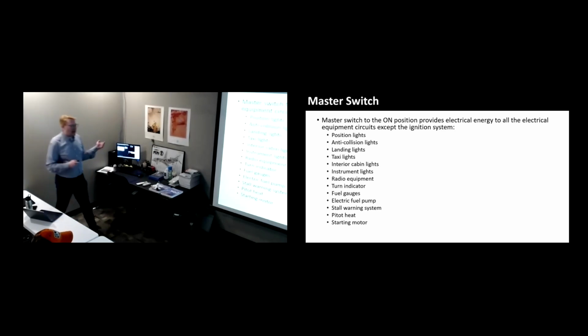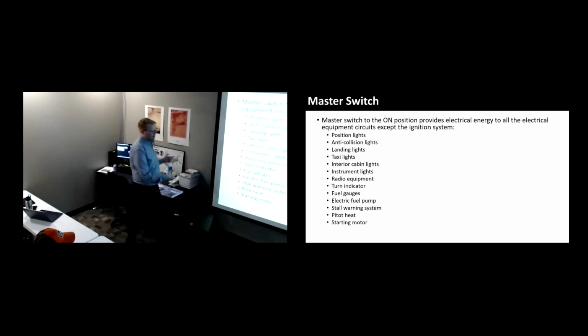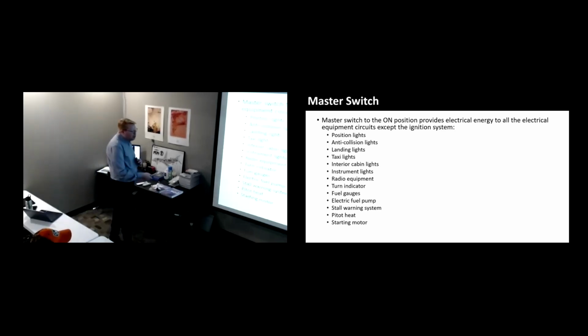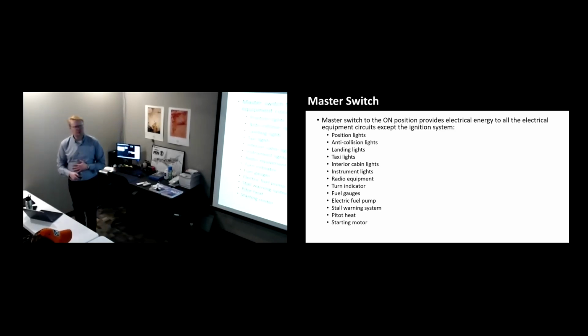Not all airplanes have these powered. For example, the stall warning system in the Cessna 172 is automatic. You don't need a power input. It's all pressure difference. Whereas in a Piper product, there's a little switch that moves that causes that system to work. Again, in the hangar, let me know. But no, this is a general understanding of what that battery switch is controlling.